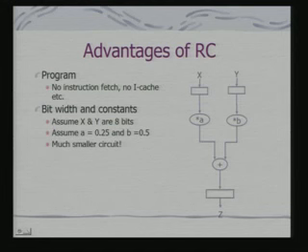So what I have got here is this multiplication and addition, and this 0.5 and 0.25 is division by 2 and division by 4, which is nothing but shift operations, and I need to do addition.